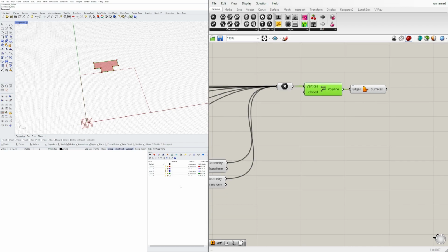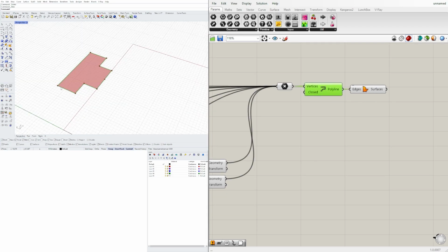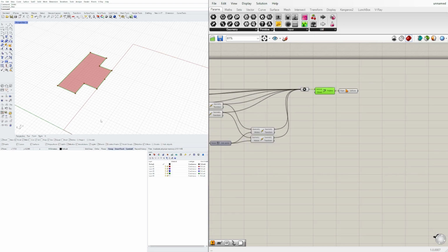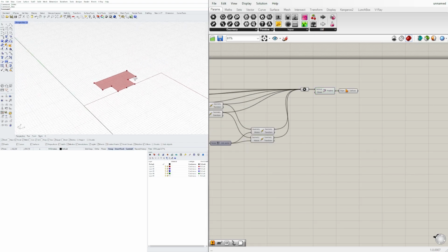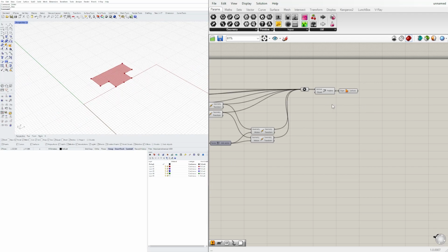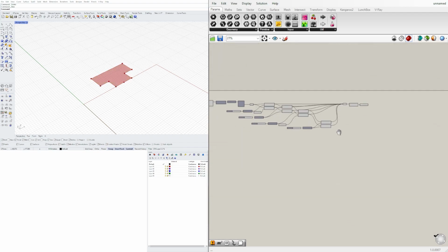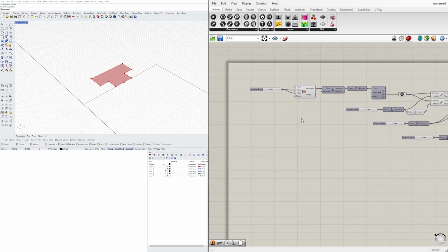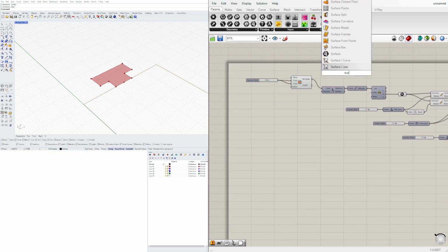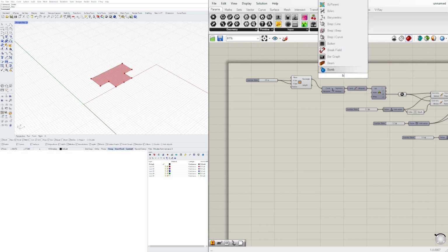And we can also do a fillet or round off the edges here and then close it. This way the connection could have this rounded off, but let's keep it simple for this exercise and I'll show you the next steps. We can always come back and further add more details to this. All right, great. So now that we have this surface, let's create a surface also on this rectangle. So I'll go here to surface or boundary surface.